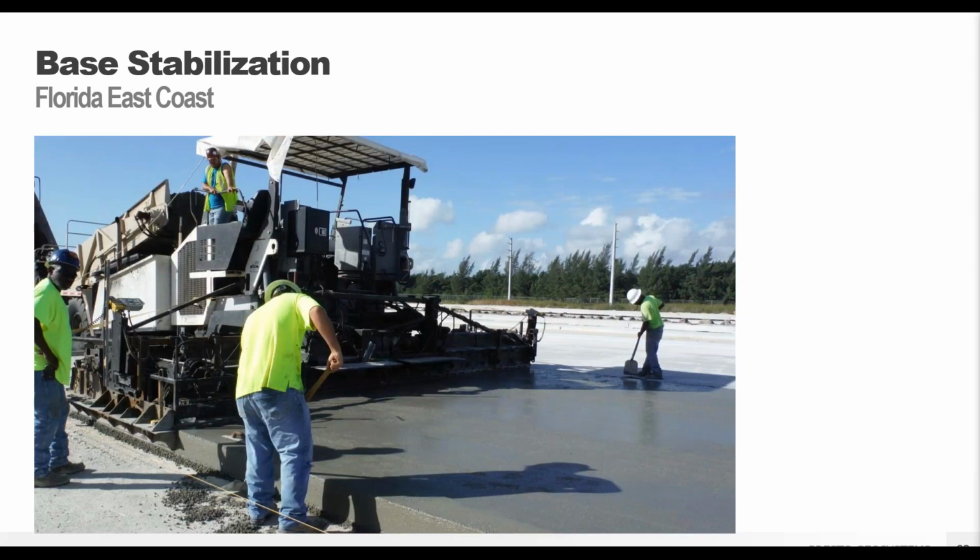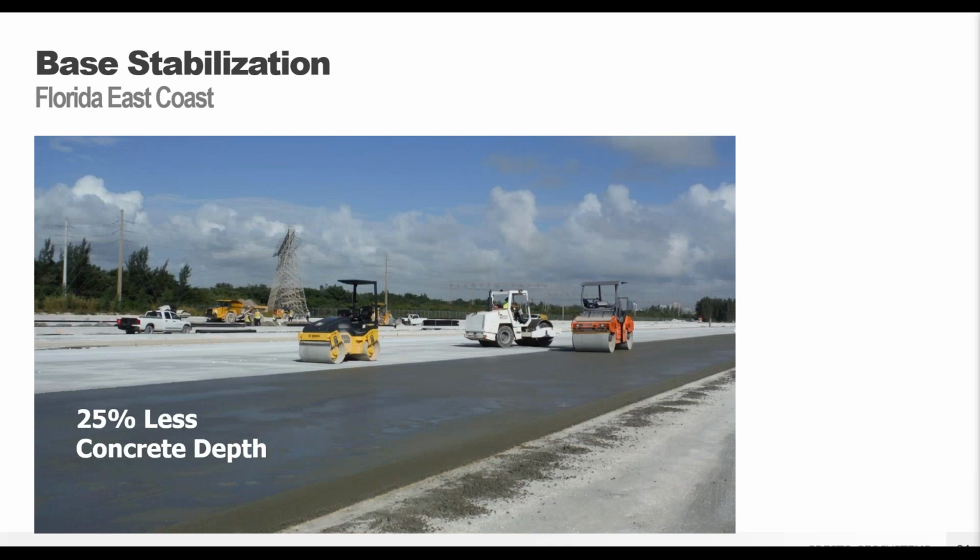And then they did roller compacted concrete on top. RCC pavement is actually sort of an interesting wear surface. It's essentially a low slump, high PSI concrete with no internal reinforcement. So it typically goes down in lifts between 8 and 10 inches. It is becoming a lot more popular in intermodal and port areas, but it does have a lot of base strength requirements, which is why it's great to use the GeoWeb system underneath.